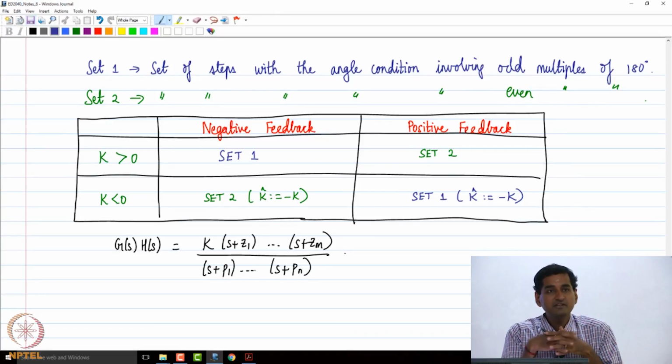Depending on your design choice, we will do a case study tomorrow that will run through the entire process. Now that we have done with root locus design, I will take a physical problem, we will start from the beginning, derive a mathematical model, get the plant transfer function, then try to design controllers, find out what ranges of controller gains will stabilize the closed loop system, and then how to construct the root locus to satisfy certain performance requirements. As we would have already realized, the root locus provides us with a graphical representation, so we can immediately see how easily we can get the ranges of controller gains that would satisfy performance requirements.